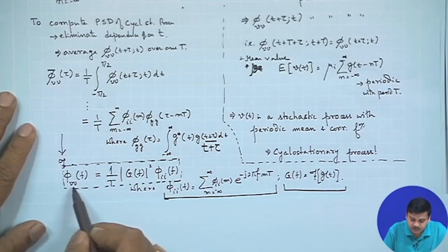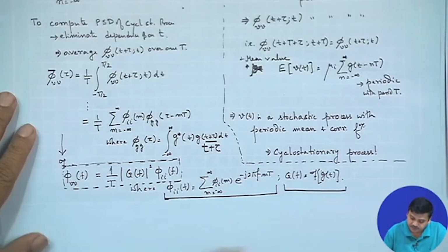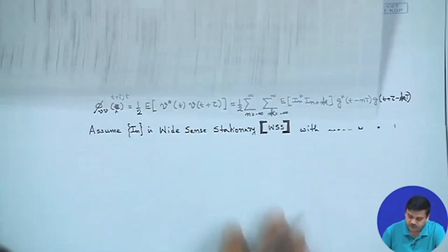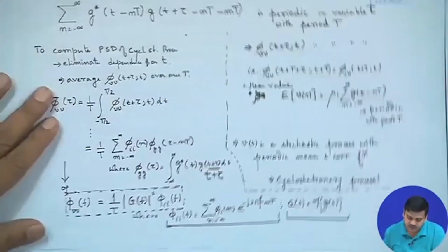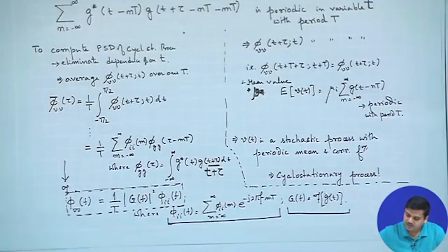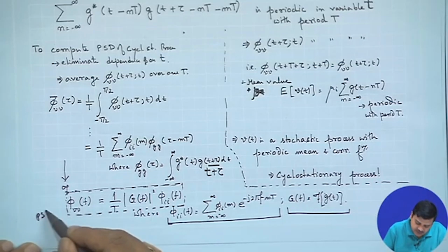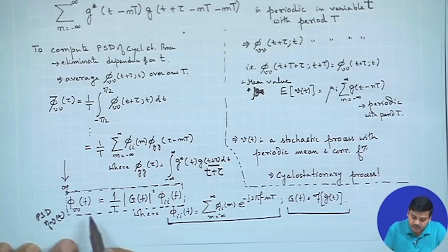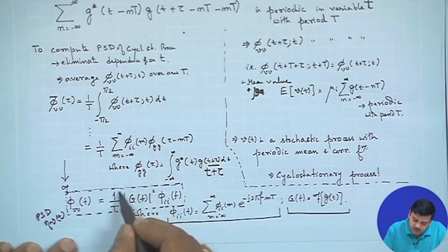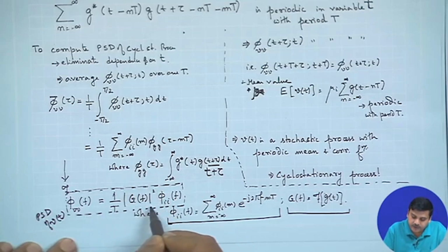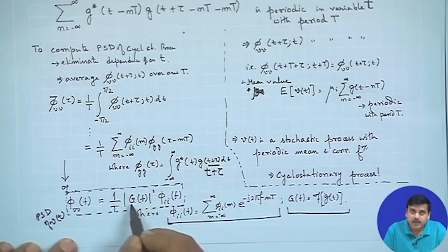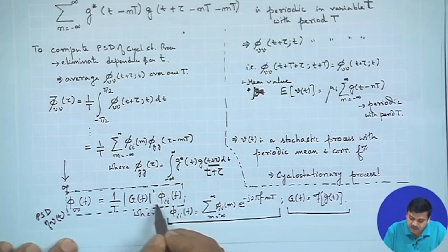Now, we call the signal a stochastic process because it is being modulated by the information bearing signal. Now, what we get from this particular expression is something very important to note, that the PSD, the power spectral density of V(t), is dependent on the power spectral density or the frequency characteristics of the pulse shape and the frequency characteristics of the information bearing signal, right.